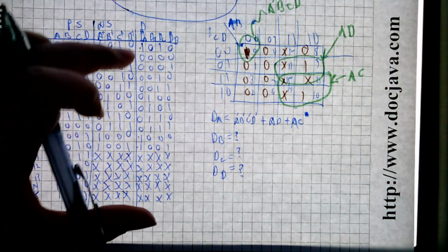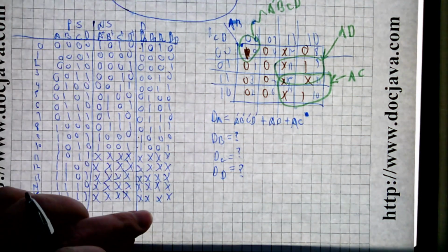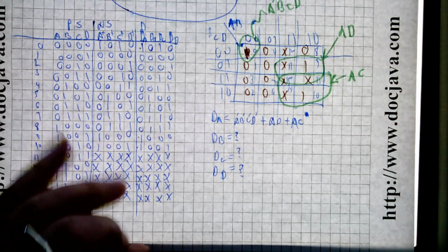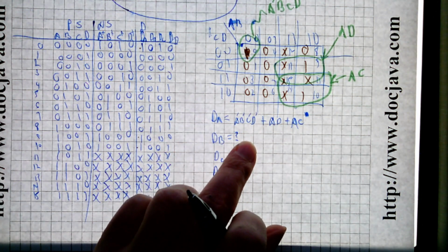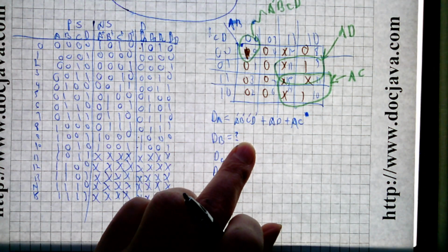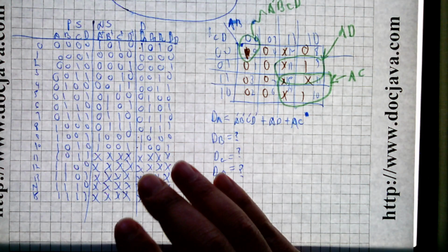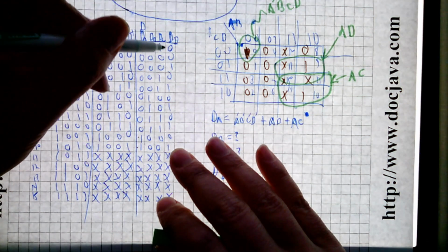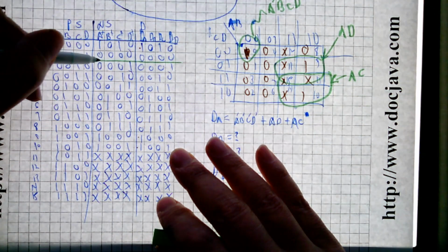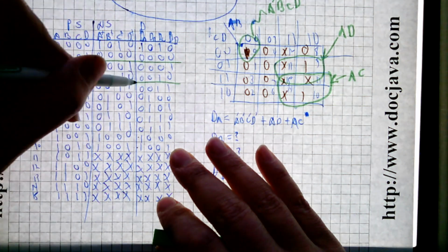Yeah, you need to go to d sub b, fill out your K-map using d sub b, loop your K-map, and get a minimum sum of products form implementation for d sub b. Having said that, you could probably do it with an 8-to-1 multiplexer if you like. If you did it with a multiplexer, how cool would that be? What you would do is divide it up into rows of 2.